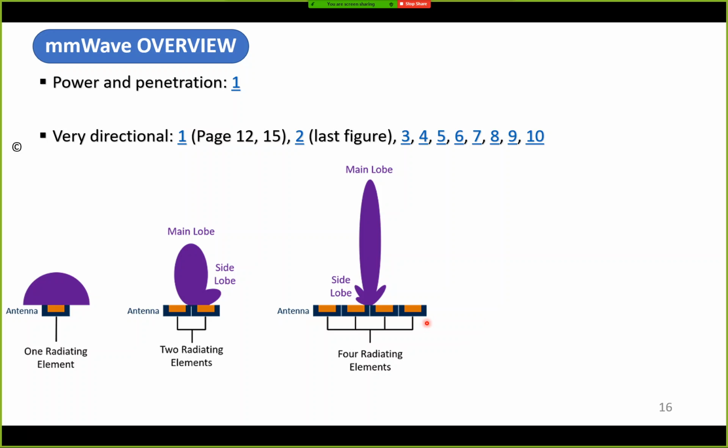So this is the idea. The idea is going up to higher frequencies. The distance it can travel shrinks, but we can make the signal more focused. And as I will mention in the next slide, we will have more base stations, maybe every 100 meters, every 500 meters. Instead of 2 kilometer, 5 kilometer, 20 kilometer base stations, we will have mini base stations more often.